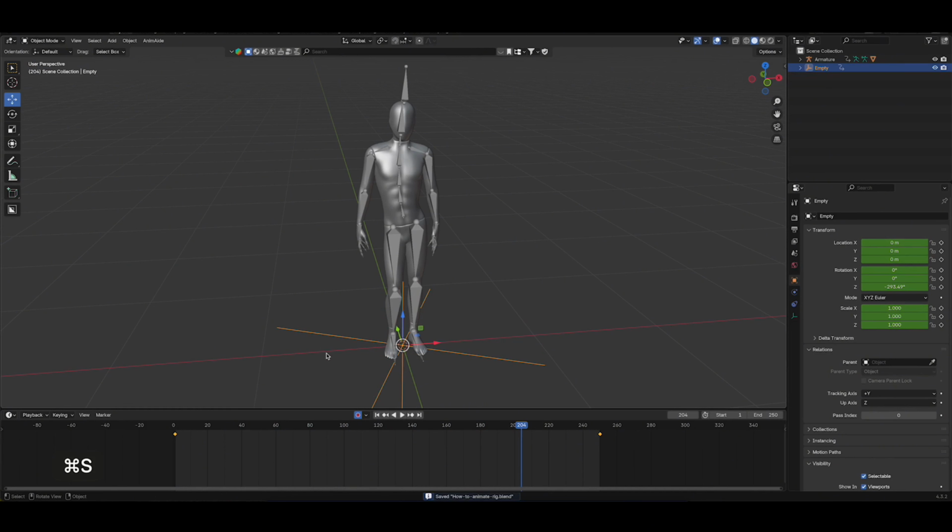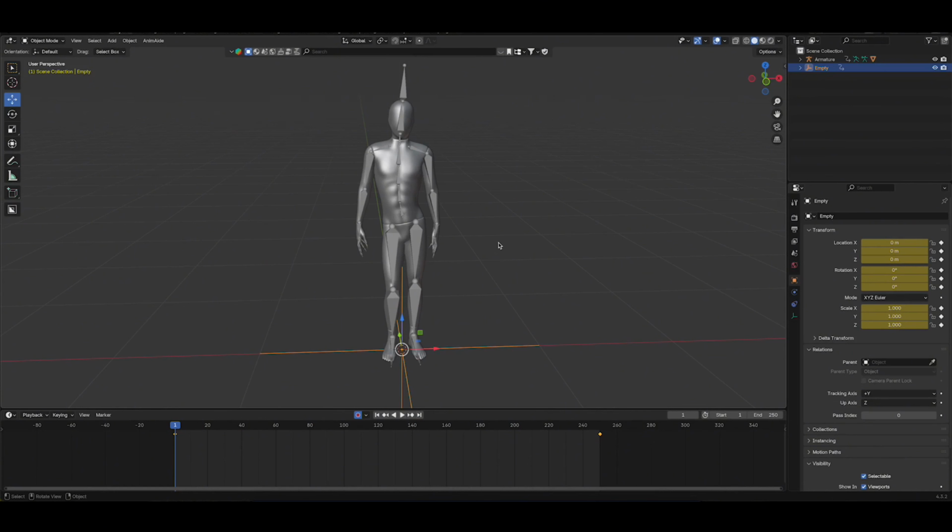Awesome. Don't forget to save your file at every process in order not to lose your progress. Now it's a perfect time to animate our avatar on the rotation of our pivot point. First of all, we need to connect our armature to the pivot point, because you can see that the pivot point rotates, but our armature doesn't.